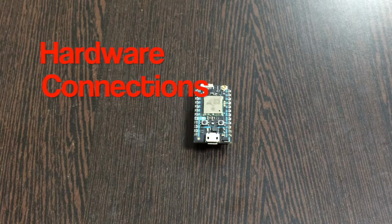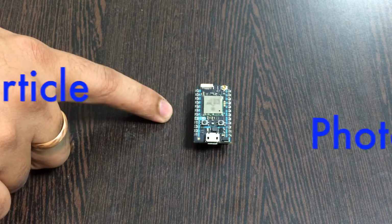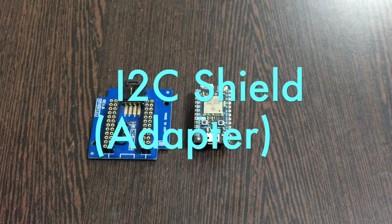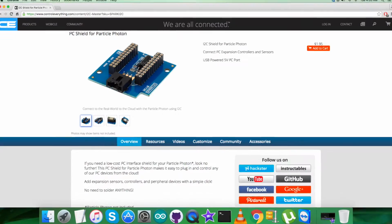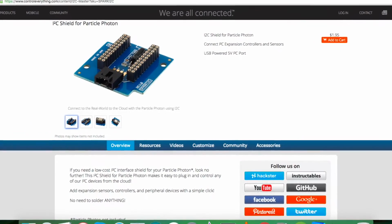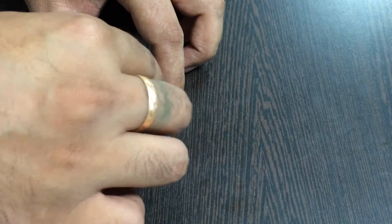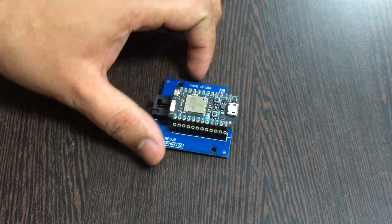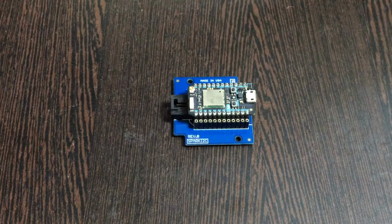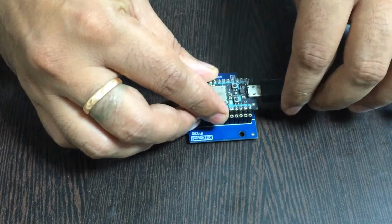Well, coming to the hardware connection setup part, the first thing we require, which you are able to see on my screen, is a particle photon. Now this here is an I2C Shield. It's available and can be purchased from the website controleverything.com, and the reason we are using this shield is to make connections easier with other I2C devices. So for that, what we require is to gently place this particle photon over the I2C shield and make a connection just like that. Now to power up this particle photon, what we require is a micro USB cable, which you can see on my screen, and gently insert it over this power jack.